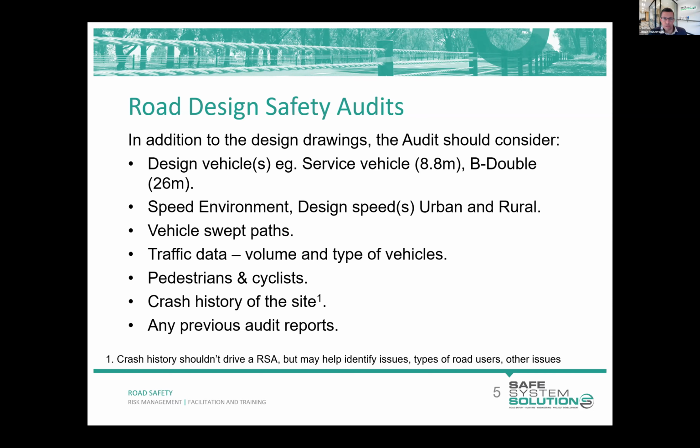The crash history of a site, and we've got a little bit of a disclaimer there. Some auditors don't like to know the crash history of a site. They prefer to go in with an open mind and not be influenced by what's happened in the past. Crashes on our roads often do occur in a random fashion. So if that's the case with our crash history, we don't want to be influenced by that too much. But certainly if there is a trend of a particular crash, you want to know that your design is going to address that obvious problem.